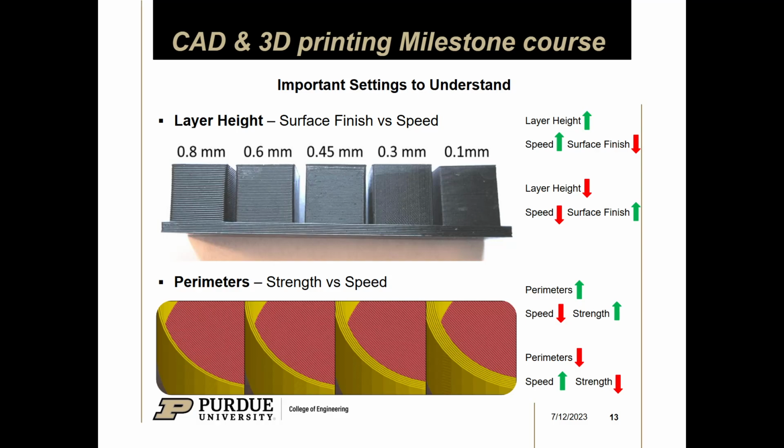But again, that can also depend on what you're making, the material you're printing, and how much strength you really need. I haven't really encountered that many issues printing at finer layer heights, but part of it is because I'm using pretty strong materials. Also, I'll be talking about print orientation in a little bit, but that also plays a big role in how strong your part will be.